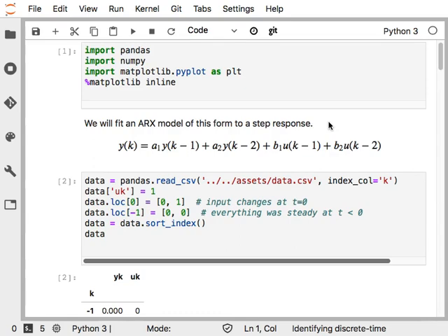We're going to dig into discrete models in a great deal of detail later, the analysis, and also we've got a special notation that makes all of this easier. The piece that I want you to understand today is just that writing equations in this difference equation form allows us to identify these parameters using linear algebra techniques. And it's the modern standard for process identification.